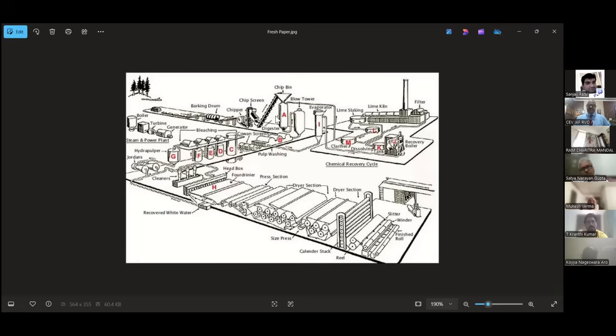In a digester, many times there is an undigested part also, just like knots, something which is not fully converted into semi-liquid form. So it goes to the various screeners where all the knots or undigested parts are removed and again fed to the digesters. And purely pulp in a viscous or semi-liquid form comes into the bleaching process.